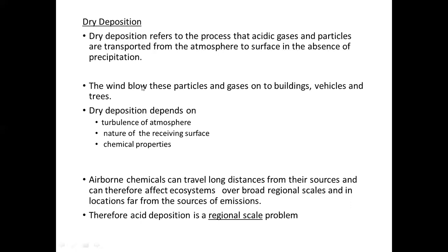Okay, so the wind is responsible for that. Wind blows these particles and gases onto buildings, vehicles and trees. So dry deposition depends on the turbulence of the atmosphere, the nature of the receiving surface and the chemical properties of the receiving surface or the gas. So airborne chemicals can travel long distances from their sources and can therefore affect ecosystems over broad regional scales and in locations far from the source of emission.